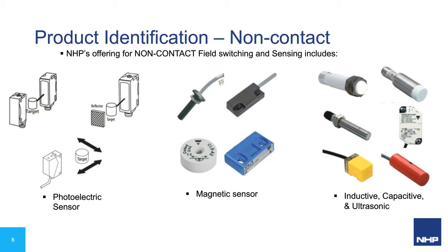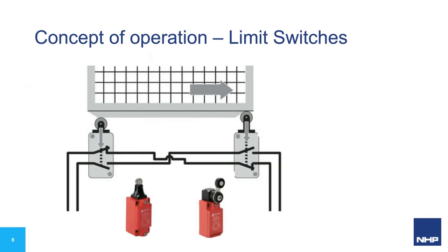So limit switches have an actuator that needs to be moved by the object or material that is wanting to be detected in order for it to work. So the actuator is connected either directly via a shaft or plunger to the contacts internally, or through something like a spring internal to the switch. Now, physically moving the actuator moves this shaft and plunger down to activate the contacts.